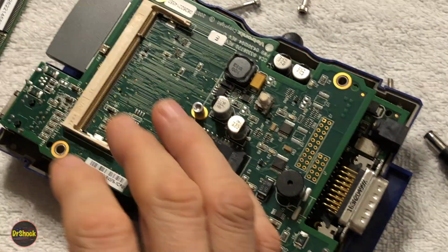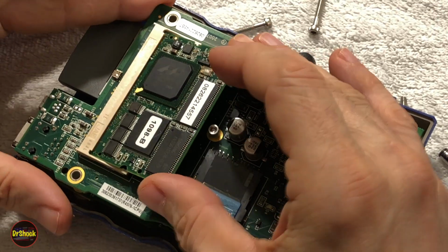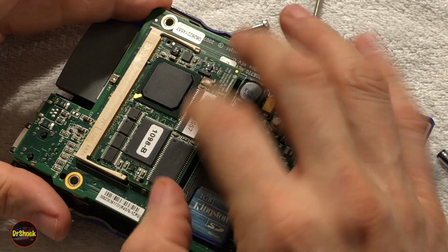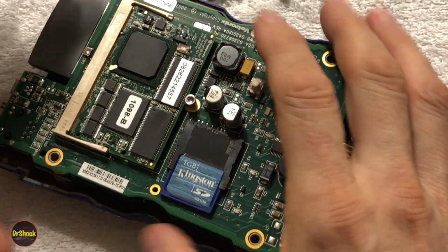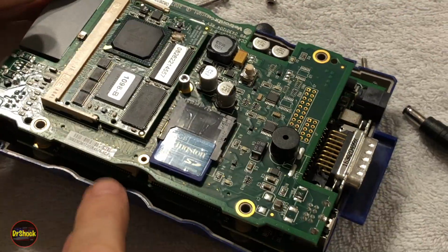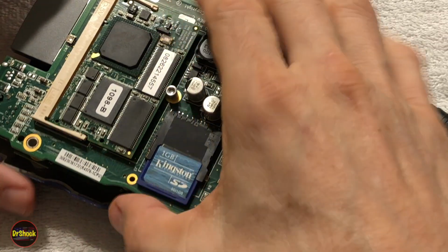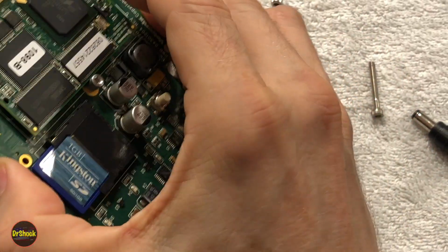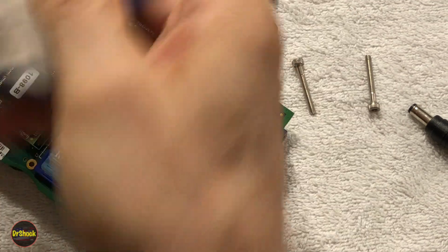So if we had been able to repair it by swapping out this board, that would have been a possibility. Sometimes you can find these boards like on AliExpress, and that would be a way to repair it. But in this case, we again most likely have the problem is the FPGA board. But we're not 100% sure. So what we're going to do is we're going to do a different test here. So I'm going to pop this guy out.